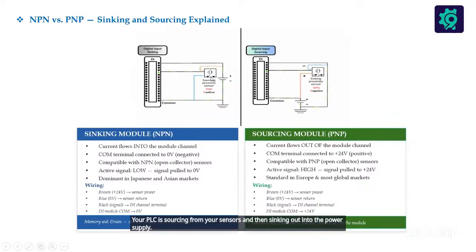But for your sensor, you can see that it is sourcing from the power supply while it is sinking into the PLC. Okay, it's sourcing from the power supply and then it is sinking into the PLC. So if you look at this end, you will see, based on the flow of signal, that your PLC is sinking into the sensor while it is sourcing from the power supply. But for your sensor, it is sourcing from the PLC while it's sinking back into the power supply.